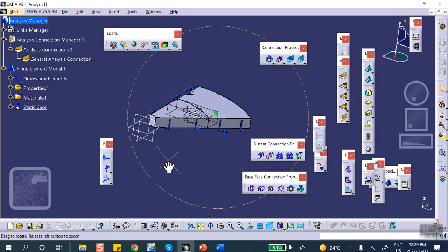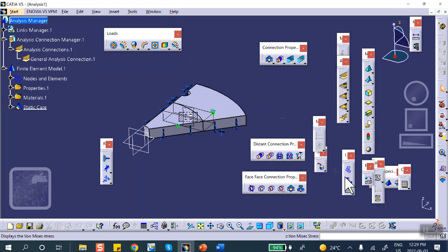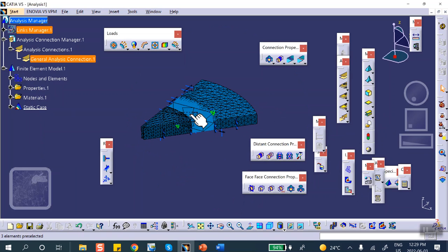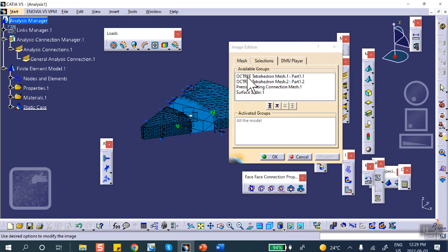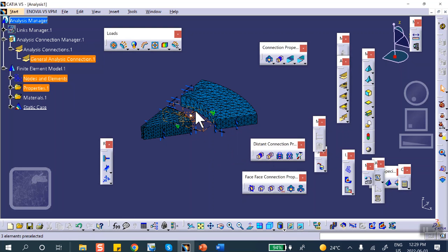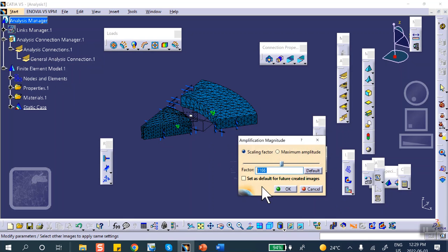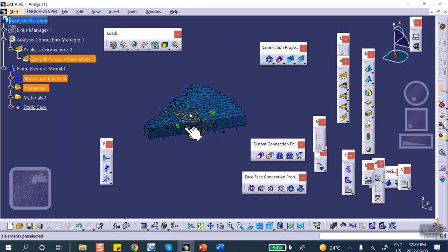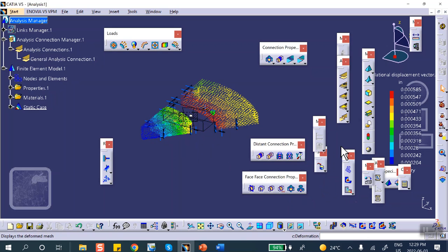Don't worry about that. If you look at the deformation, it looks like this. And this gap appears because of the graphical illusion. So if you wanted to see it without the gap, first of all, let's get rid of all those extra internal elements. So there we are. And if you want to see the true scale, you go and change the scale to 1, and they're going to be touching each other. It has to be. Okay.